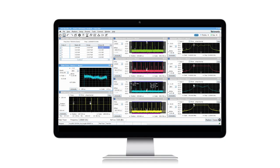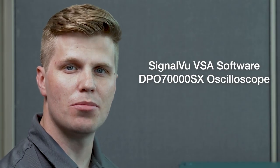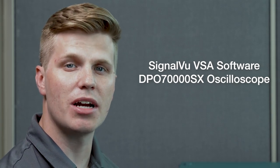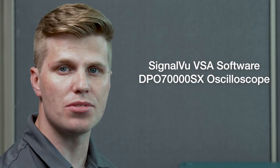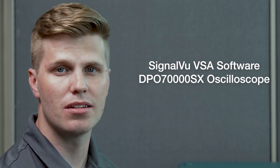In this video, we showed you how you can gain a thorough understanding of a typical MIMO phased array radar system. SignalView version 5.3 now supports multi-channel analysis for enabling phase-coherent analysis of multiple signals simultaneously. Combined with the DPO-70000SX oscilloscope and fast-frame segmented memory capture, you can quickly analyze minute changes over thousands of pulses, over multiple channels, over time and frequency domains.